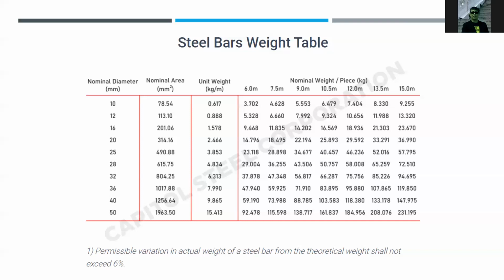Or maybe you can buy a 15 meter bar and cut it into two. So it will depend on the cutting sequence, the cutting list that you will arrive at for the beams, or maybe for the columns, in case you will create a cutting list for the columns.